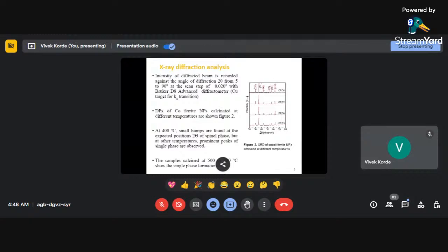Okay, and after that, one can examine its crystalline nature from the X-ray diffraction methods, from the obtained peaks and their corresponding intensity and the angle of diffraction. One can correlate their X-ray diffraction pattern with the standard one and proceed to decide whether their material is formed or not. So the X-ray diffraction technique is very important in the field of material science, which is the first technique to decide whether the material is crystalline or not, and depending on that we can decide whether we have to proceed for further steps or not. Okay, so please go ahead.